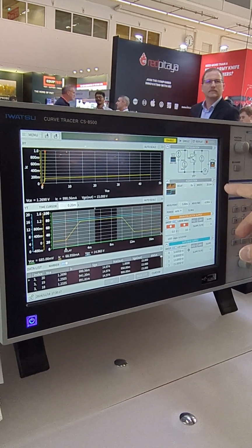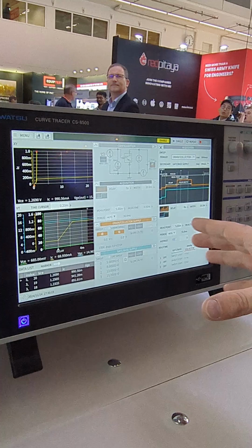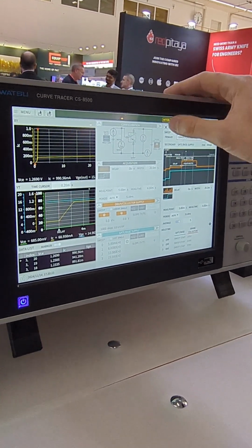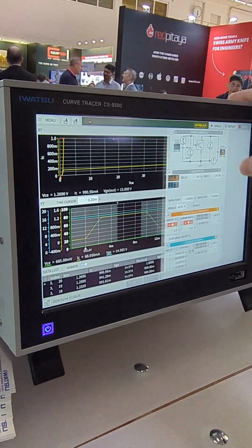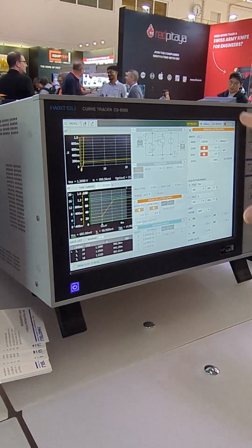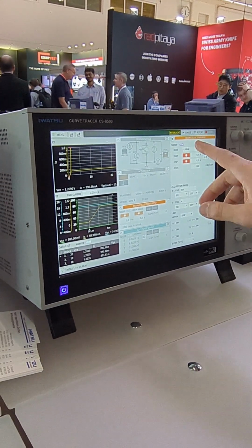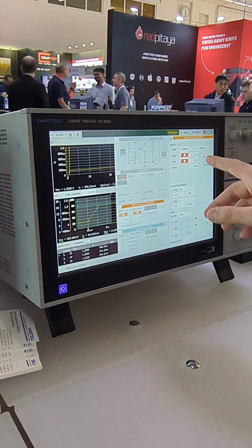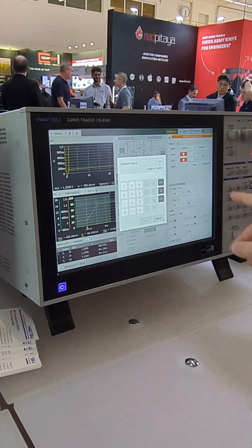Then I get to the next one, I just do the acquisition part. So I set the delay, the pulse width, the measure point, the measure time. And then I'm already here for the drain collector supply. So if I want to do a sweep, if I just want to have a linear DC voltage, I want to sweep, for example, from 0 to 10.